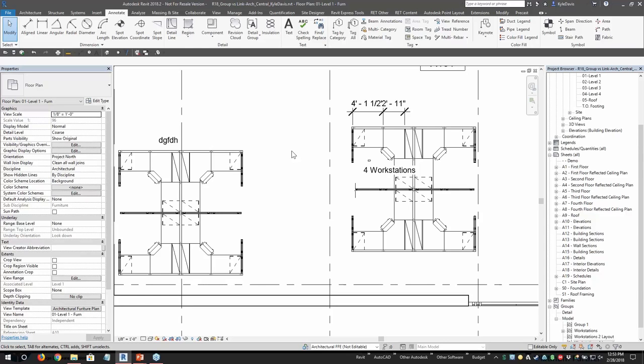Groups are beneficial, I think, for smaller stuff. When you group furniture and things like that, it's faster than creating those as a link. One issue I ran into with creating a bunch of units as a group was that I had a pretty good sized apartment building I was playing with, and the groups actually slowed the model down a little bit more than links. So if it's a pretty good sized apartment building, you might consider links for the interior unit. But then you have limited ability to exclude an element from that model, which you can do with groups. So you might have to save the link as another link.